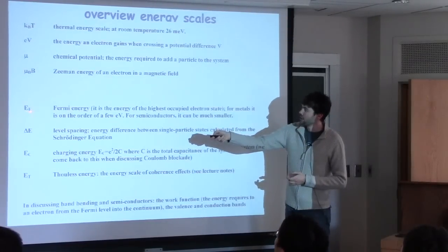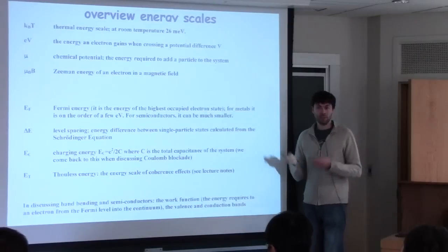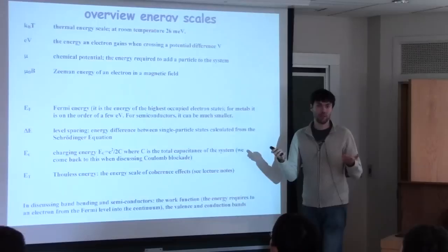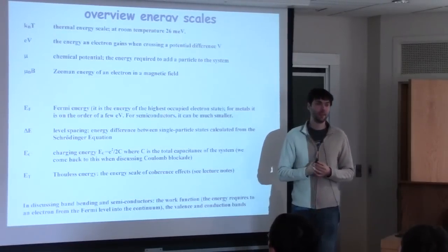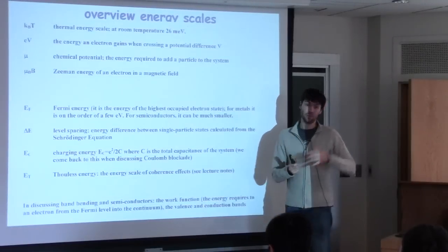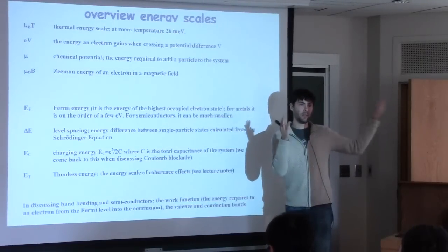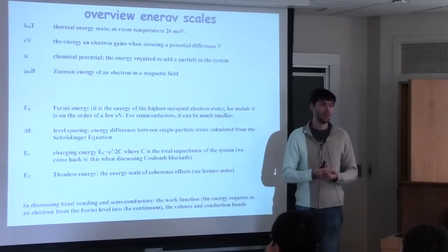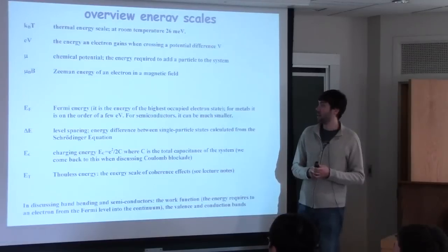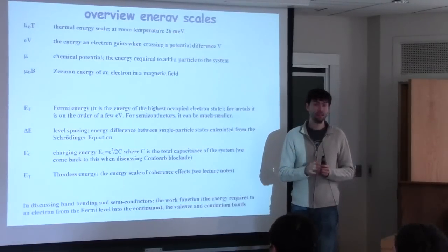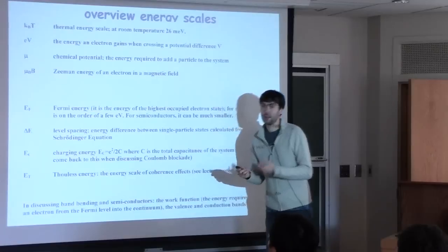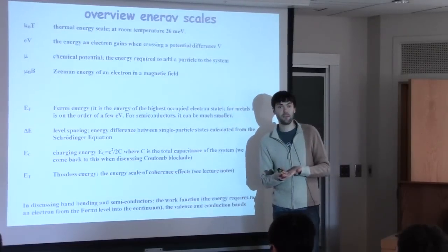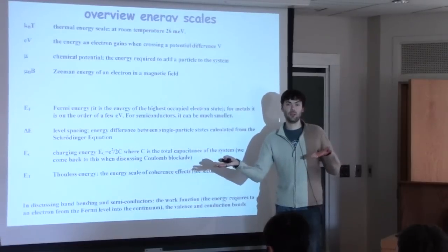Now, this one is very important. Electrons are fermions, and so if it's not a confined box where we have to talk about quantized levels, then electrons, for example in your source lead, where you have billions or Avogadro's number of electrons, would occupy all states up to the Fermi energy, right? Everyone knows that, right? Who doesn't know the Fermi energy? Okay, so the Fermi energy is the energy that the electrons have in the source or in the drain of a nanoscale device.